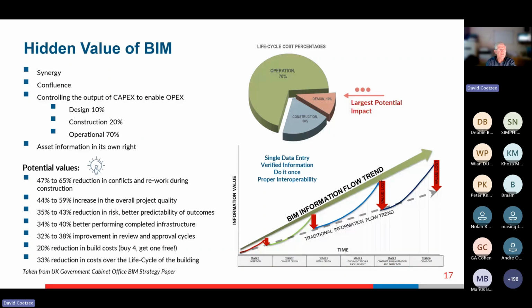Not all clashes are issues. Some clashes are expected. One of the things I have trouble explaining to non-technical people is why the concrete and steel models are showing 2,000 clashes every week. That is really because the holding down bolts in the foundation pads are part of the steel model, but they're embedded in the concrete.